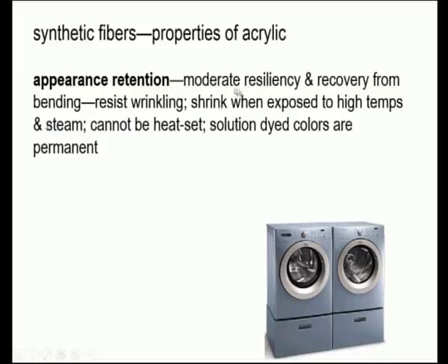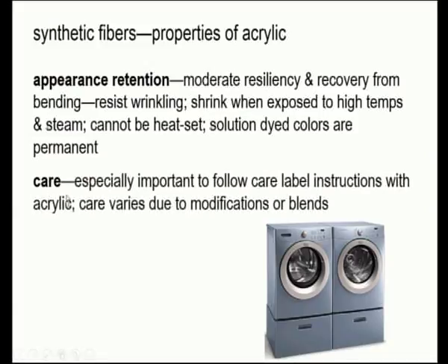Appearance retention: moderate resiliency and recovery from bending, resists wrinkling, shrinks when exposed to high temperature and steam, cannot be heat set, and solution dyed colors are permanent. So, whatever dye we are using, it is going to stick permanently. What care do we have to do? It is especially important to follow care label instructions with acrylic. Care varies due to modification or blends.